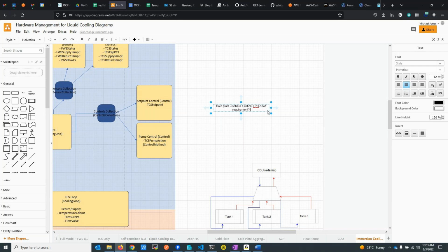But you still have an issue if the dielectric coolant gets too hot, it can get dangerous. So if there is some problem with the electronics temperature management loop and the servers don't shut themselves down and you don't have enough cooling from the CDU, you could end up with a dangerous condition from overheating the dielectric.